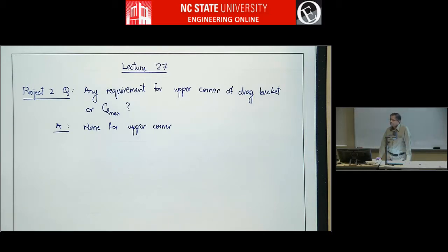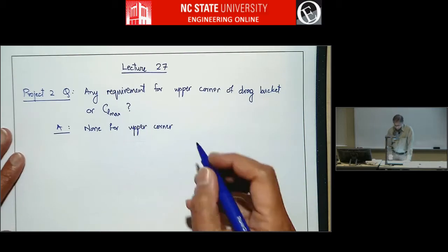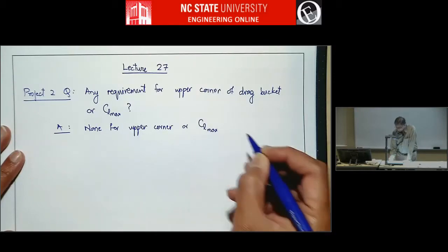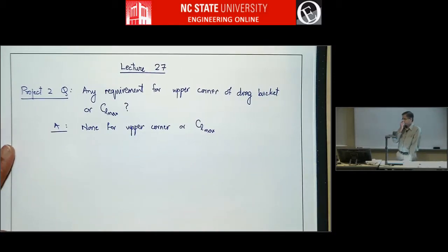Okay. And then one more thing. I was having trouble. It was fine for the 50% or favorable gradient for positive angles of attack, but I noticed that at negative angles of attack, on my lower surface I had a hard time getting a favorable gradient. It would be adverse. So the question is, at negative angles of attack, you're not getting a favorable gradient on the lower surface. Yeah. That's when you fall out of the drag bucket. Okay. That's sort of associated with getting out of the drag bucket.